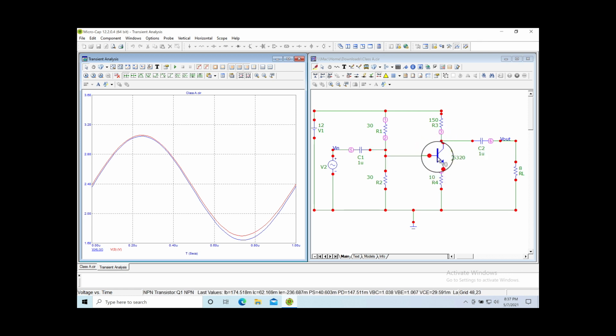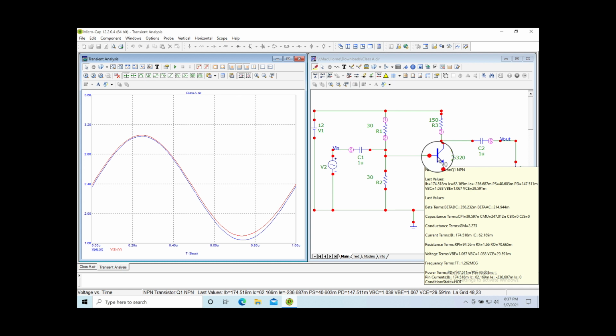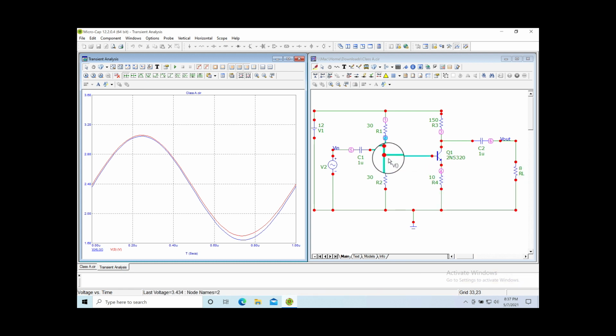This transistor, it's on. It's just pretty much solidly on. And this guy's wiggling, and both this and this side is just wiggling along with it. So we don't get any gain with that, right? But they are in phase. We are getting current gain because we have plenty of current for 8 ohms. But yeah, so this circuit here, a little bit too simple maybe for a real amplifier.